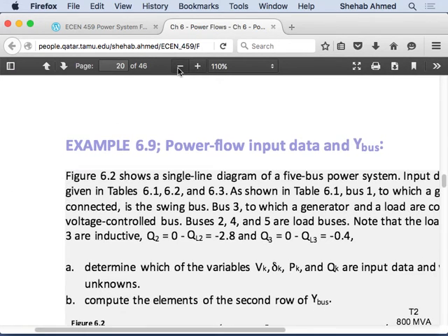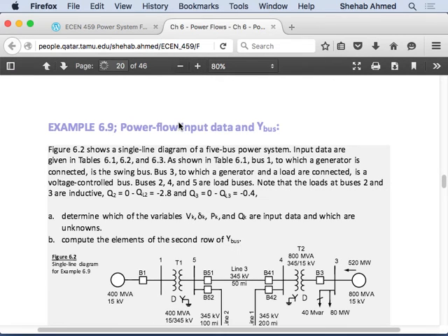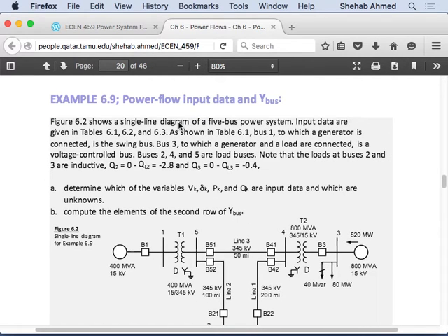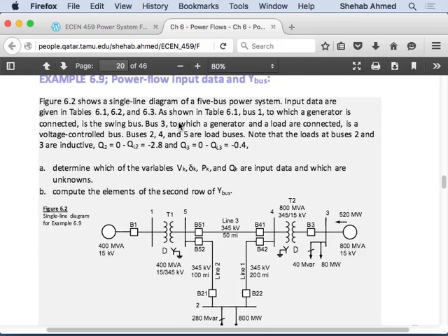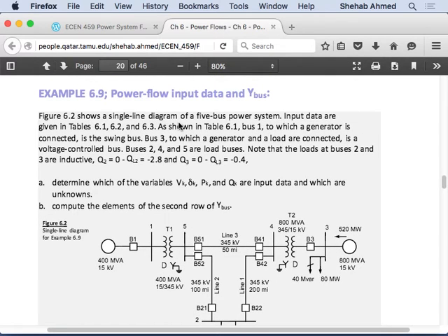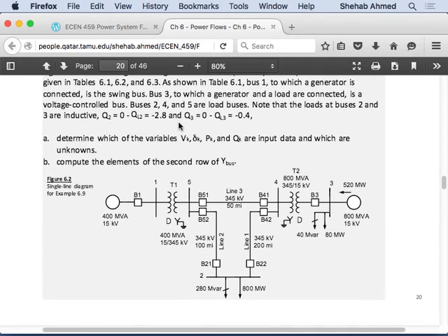And this will, of course, affect the order of the matrix in which I will plug all these equations, right? I will be plugging all these equations in matrices, right? So that's why I said the order of matrices is important, because of the Y-bus matrix, its order is the order of the system nodes. So if it's a three-bus system, it's a 3x3 matrix, the Y-bus. But the matrices that we will build with these power flow equations, they will depend on the type of buses. The order of the matrix will depend on the type of bus. Right? So let's do some examples and it will become clear.